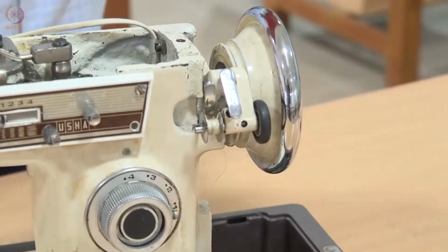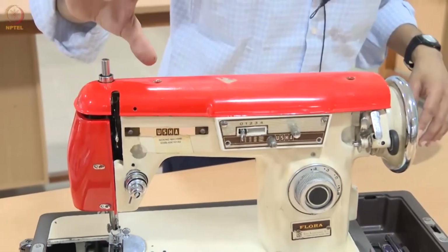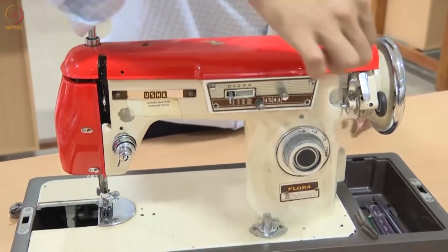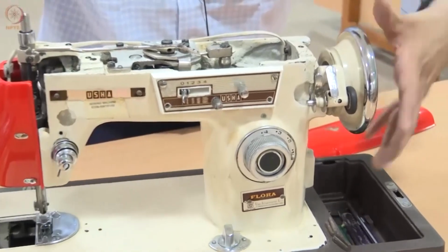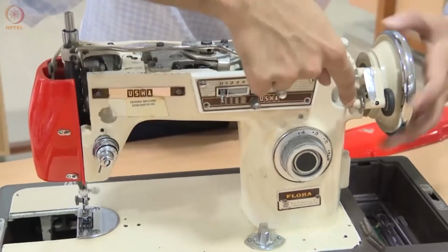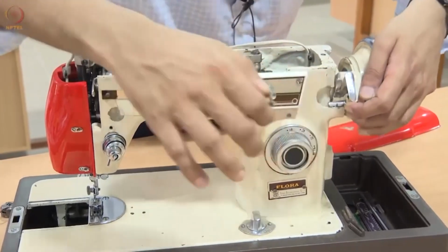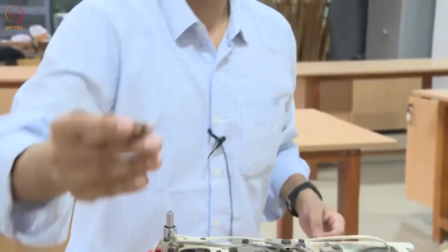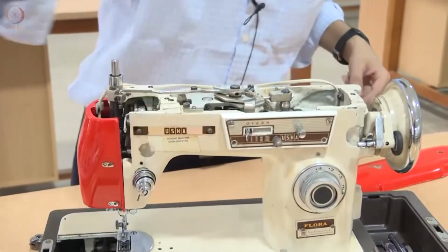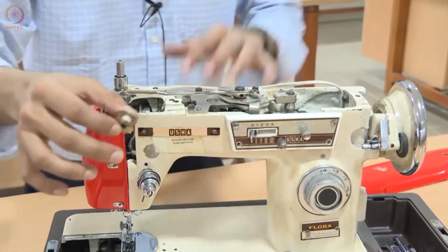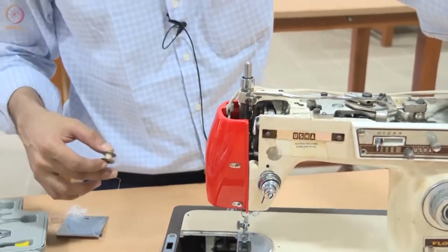So imagine on top I have another thread supply, an external threaded bobbin. I take it and then I feed it here. What happens is, this starts once I power the machine. You can see it is rotating the spool and it will start winding the spool. So now we have a very fast way to load the spool. This part of the machine helps us to quickly thread the spool. Once we do that, we have to do it for the top spool and the bottom. Both spools have to be wound using this mechanism here.